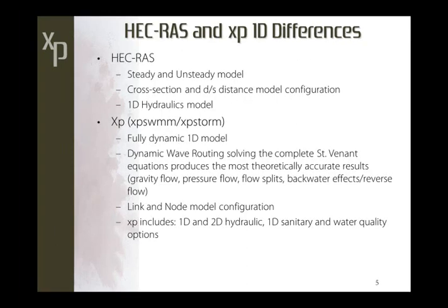And so the differences between HEC-RAS and XP 1D. For HEC-RAS, there's a steady and unsteady model. These solve primarily the momentum, energy, and continuity equations. The HEC-RAS model is a cross-section and relative downstream distance model configuration. Also, the HEC-RAS model is purely a 1D hydraulics model.